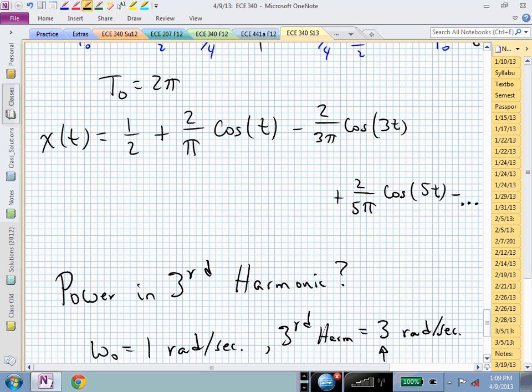observational or experimentally obtained answer. So you would need to make sure that your bandpass filter was narrow enough and steep enough in terms of its roll-off into the stop bands. But yes, that's essentially what you're doing. You would be wanting to isolate specific harmonics by bandpass filtering that x of t.